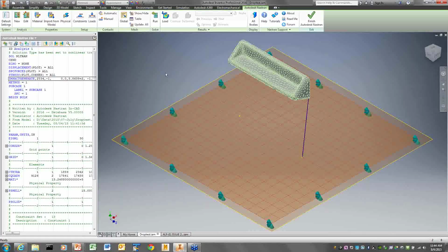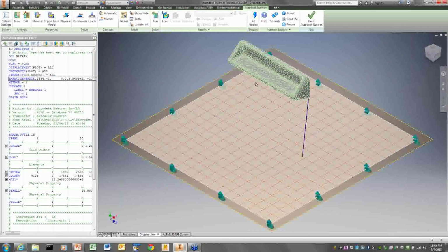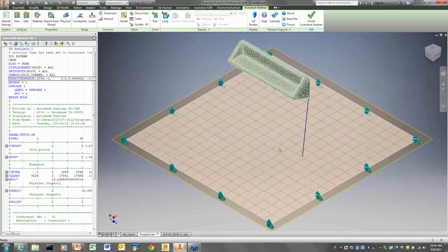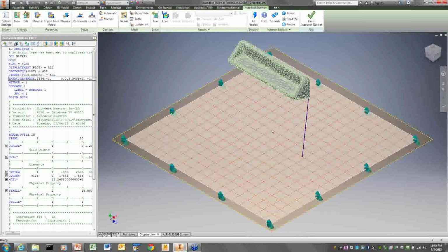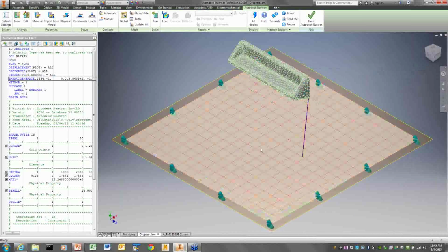And now the other thing I'll bring out here, I did this entirely using linear materials. So it's hitting here and it's bouncing off. The other thing I did was this plate down here, I modeled it as an actual plate so that when we ran it, you could see the deformations. If I just constrained all of the points on this plate it would effectively be a rigid plate. And so this would go down, it would hit a rigid surface and bounce off. That'll save you computation cycles. And if you've got something, this is plastic dropping on steel, I don't know how much deformation and flexibility you're going to get out of a half-inch steel plate. Drop a piece of plastic on it. So if you want to speed up the analysis, it might make sense to just constrain it all, and that way you've got a rigid surface that it's running into.